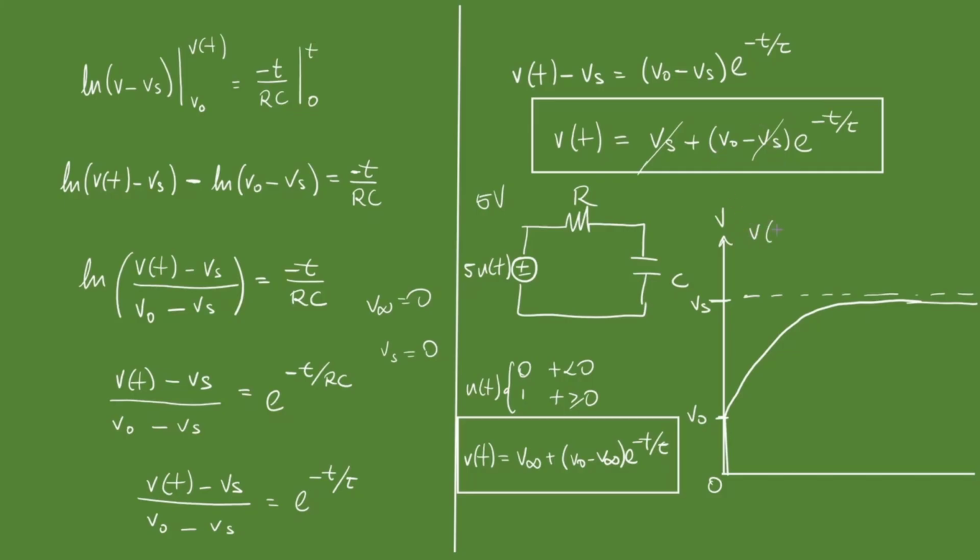So we end up with V of t is equal to V0 e to the minus t over tau, which is the formula for a source-free RC circuit. So you kind of see how the step response can simplify to the source-free response when there's no external voltage involved. So I hope that I was able to explain that.